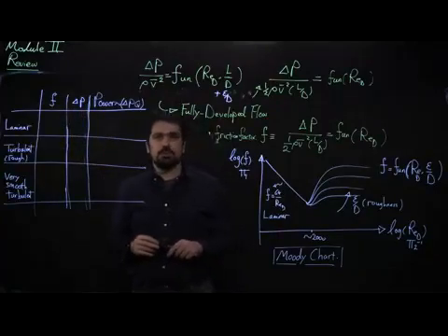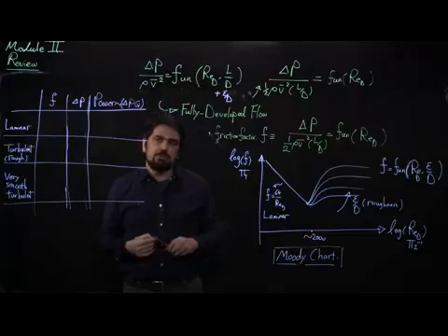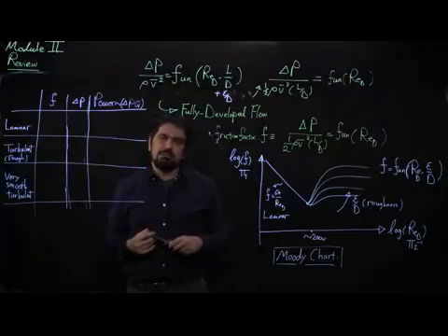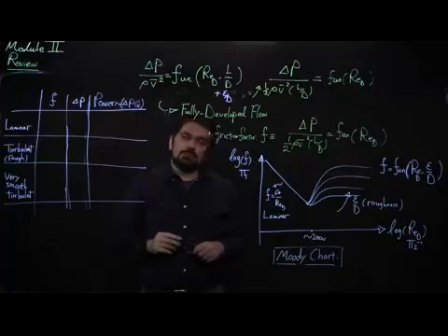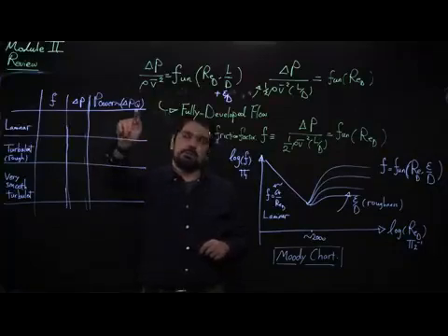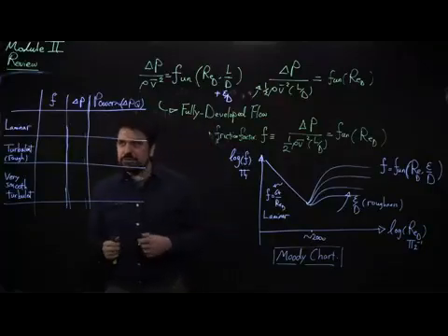Power is force times velocity, if you think about it, because it's the rate at which work is done. So it's force times a length scale divided by time, which will be force times velocity. And it is proportional in this case to nothing other than pressure times volumetric flow rate. Volumetric flow rate is velocity times area. Pressure times area forms force. Force times velocity will give you indeed power. So let's think about the scaling of these things.